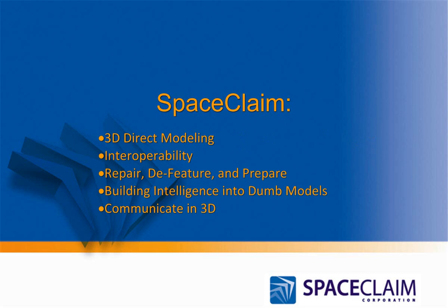SpaceClaim is a new solid modeling tool that uses direct modeling technology to let you work with 3D models in ways you've never thought were possible. It works using interactive tools that directly create, edit, and parameterize designs regardless of origin. SpaceClaim is complementary to feature-based modelers, with robust translators to read and write a broad variety of CAD formats. It provides streamlined tools to quickly remove small faces, create midsurfaces, and extract volumes for CFD.